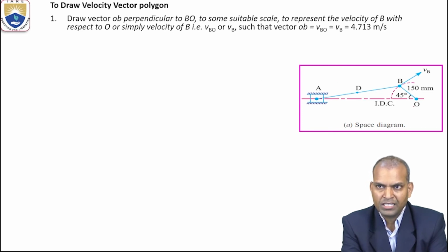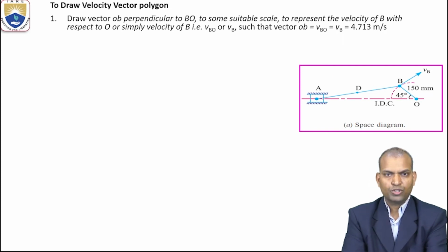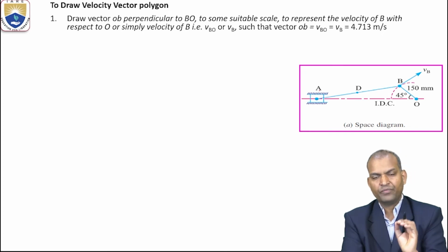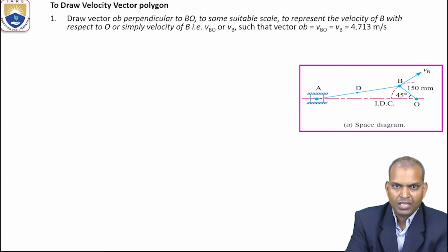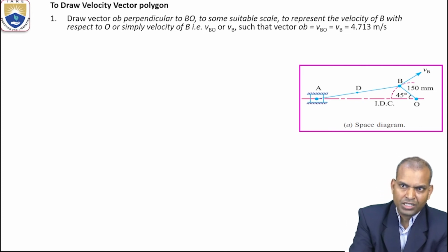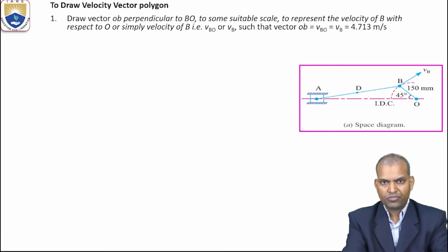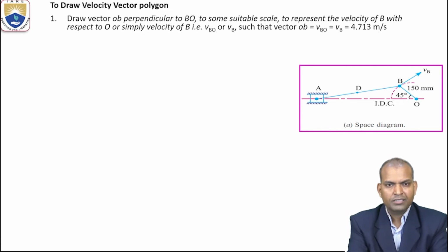That means it is 15 centimeters, and the length 45, reduce the scale by 2. It becomes 75 millimeter. And reduce AB also proportionately, and draw the configuration diagram. Redraw the configuration diagram into your answer script. Then from the configuration diagram, with the help of set squares, how to draw? You have to use either mini drafter or what? Set squares. There we need 2 set squares.